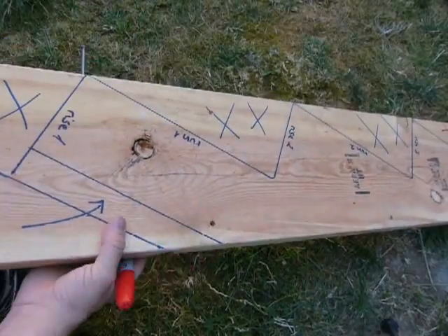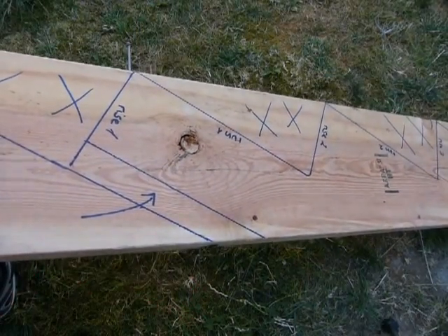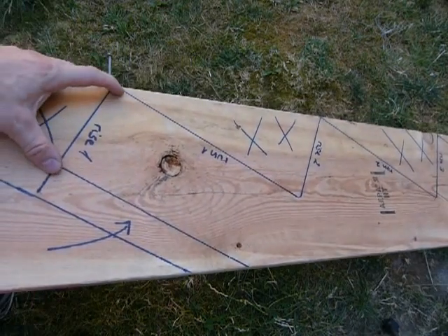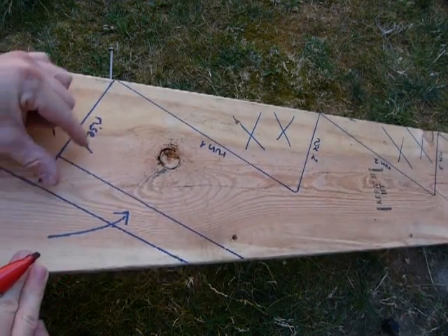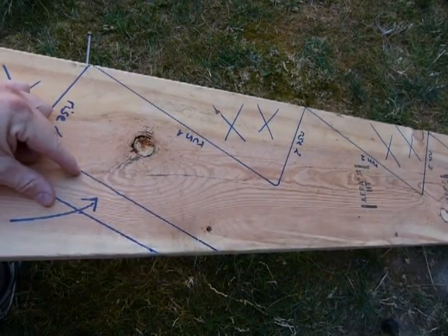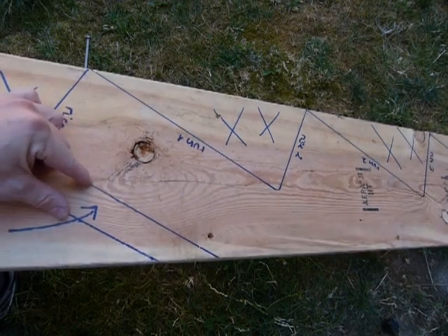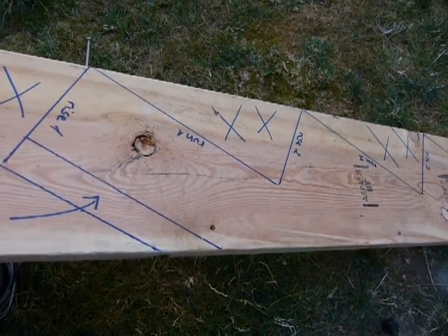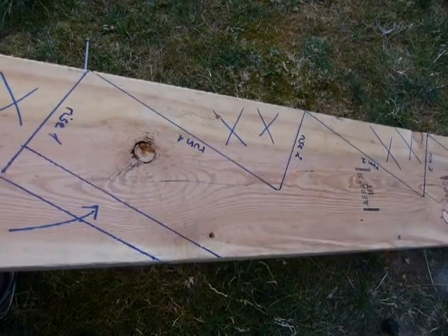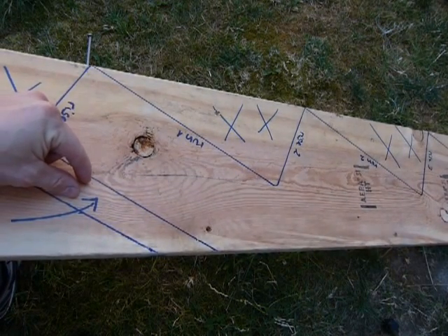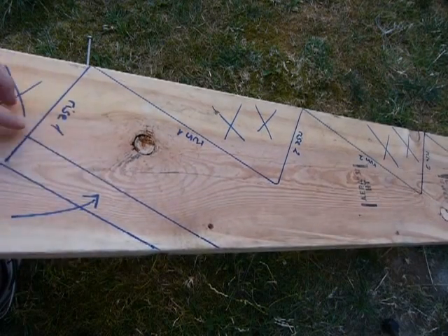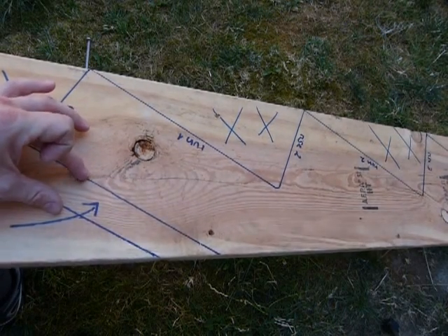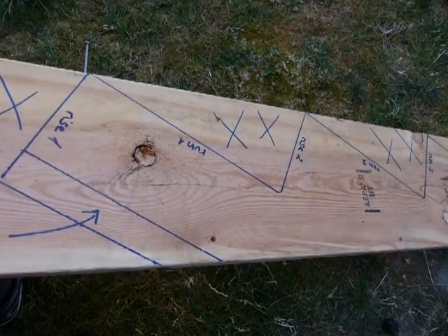Likewise, on the lower end of the stairs here, this part here is a cutaway, and I shorten my first rise by the thickness of the tread. You need to know what the thickness of the tread is. If it's 2x lumber, then it's 1.5 inches. In this case, it's 1.5 inches. And if you have plywood and finished flooring on it, or plywood with tile on it, you have to consider the thickness of the plywood, the grout or mortar bed, and the thickness of the tile. So everything here, the tread with its full final finish, has to be considered, and you have to shorten your first riser by all of this.